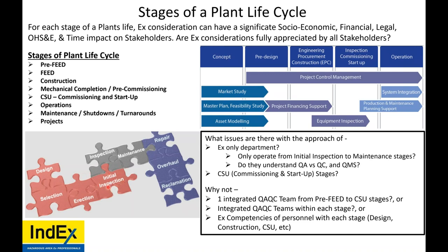Now, when it comes to commissioning, commissioning is a very interesting point just before handover. EX detailed inspections happen at mechanical completion. But from our experiences, during commissioning, many changes happen during that stage, right at that point. During that point, commissioning technicians can completely change an installation, can change the location, change an instrument. Have EX inspections taken place at that point? Do those commissioning technicians have the correct EX competencies? That is not always the case.